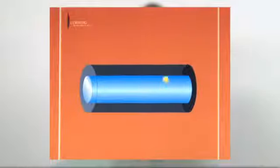This animation shows several propagating modes in a step index multimode fiber. Because of the step index profile, refraction occurs only at the core clad boundary. As you can see, light propagating along different paths travels greater or lesser distances from one end of the fiber to the other, and because of the step index, all of the energy propagates at the same speed.